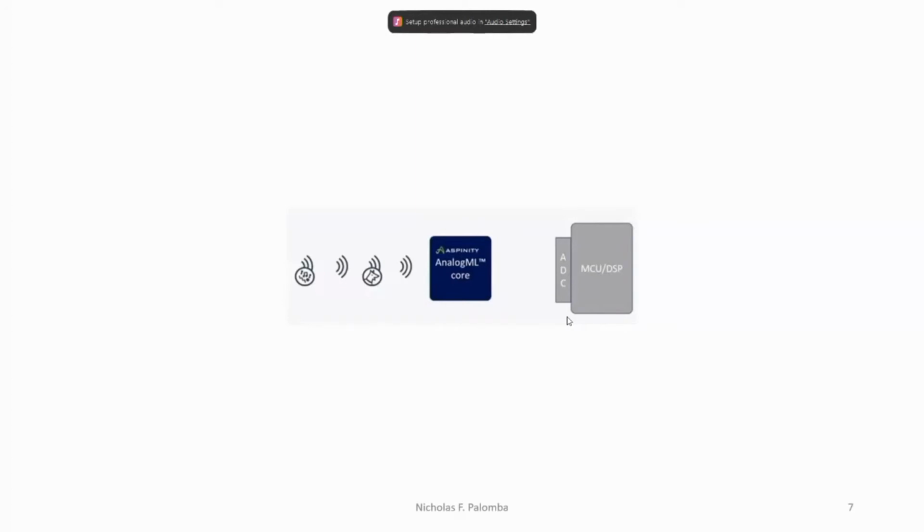So these analog machine learning chips operate completely as analog circuits with no clock required, and use raw analog data for inferencing and classification. So basically the importance of data is determined before spending any energy on data conversion and waking the associated digital processor. So clearly these three options offered by the author can be combined to offer practical solutions.